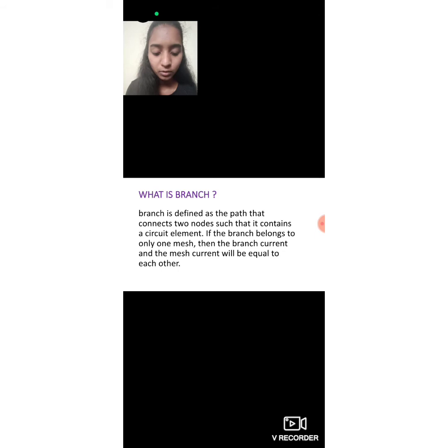The procedure for analyzing a circuit with the node method is based on the following steps. Clearly label all the circuit parameters and distinguish the unknown parameters from the known. Identify all nodes of the circuit. Select a node as a reference node, also called the ground, and assign to it a potential of 0 volts. All other voltages in the circuit are measured with respect to the reference node.